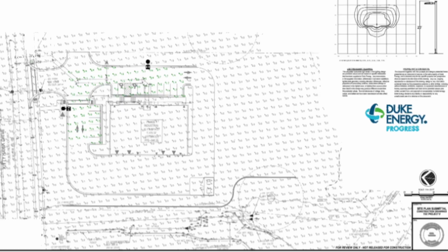As part of the grading and drainage plans, there are usually a couple of engineering sheets that show storm drain profiles and a large view of the stormwater control measure, often as an above-ground pond, and sewage pumps or risers if the site can't gravity flow to the existing public sewer line. The project site lighting plan is another common document. The plan shows the heights, locations, and type of light fixtures on the property. It will also show the intensity of the light on certain parts of the project and building.